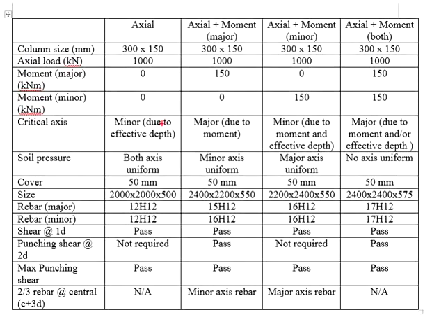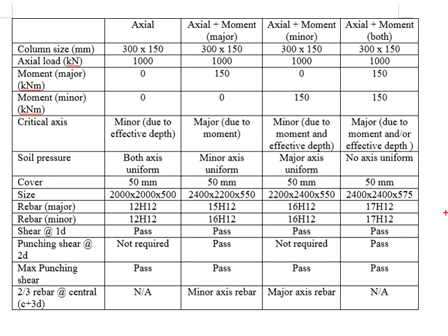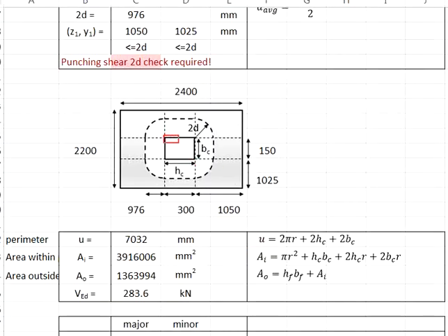And then if you observe the 4 different examples here, you realize that sometimes we don't need to check for 2D perimeter punching shear. For example, this and this. However, sometimes we will still need to check this. You might want to ask, why does changing the direction of the moment result in 2 different outcomes? The main reason lies within the orientation of the column.